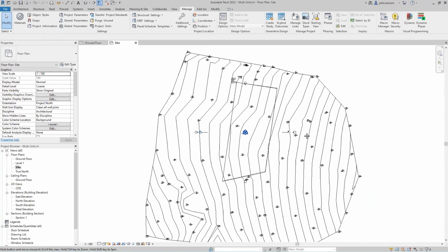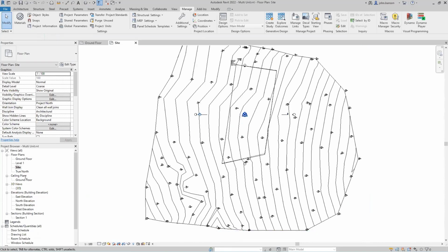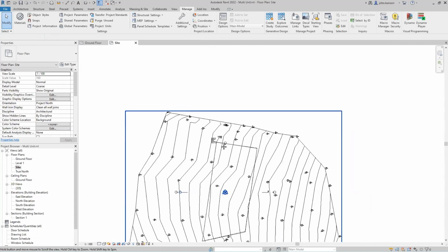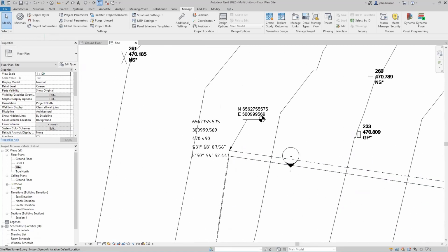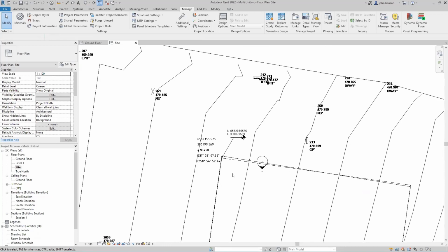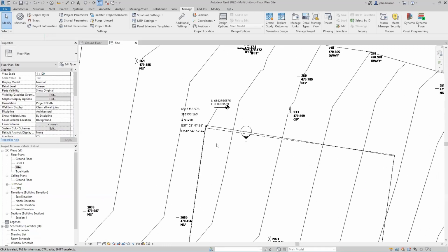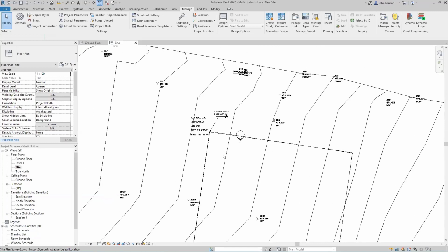So the next thing I'm going to do is, well, first of all, you'll notice that on our Civil 3D drawing, this job is based on a job done in Tamworth that I did a while ago. And Tamworth is roughly 470 metres above sea level. Our drawing that we've done in Revit is on level 0, so it's 470 metres away.